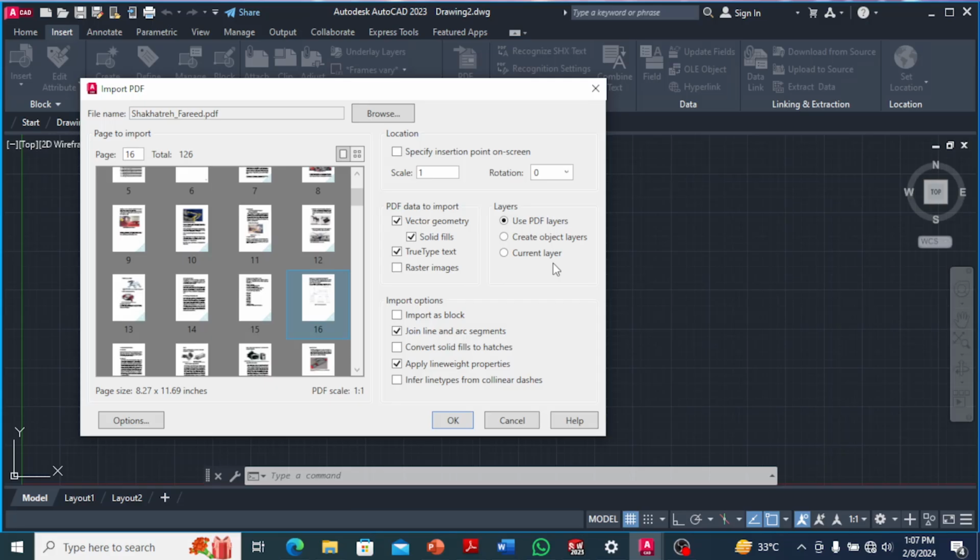It automatically turns these materials into solid fills. So you have to know how to get your way around it. And your text, there are so many calligraphy styles out there. So whenever you are importing from PDF to DWG, some text, some calligraphy might not be found, or some are automatically handled in Autodesk AutoCAD. So make sure this box is checked. It automatically updates your text, like the same calligraphy, the same style.